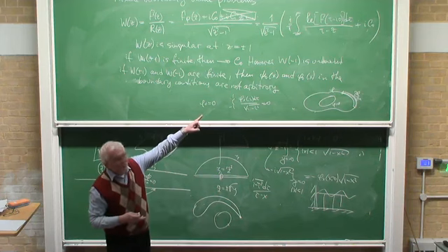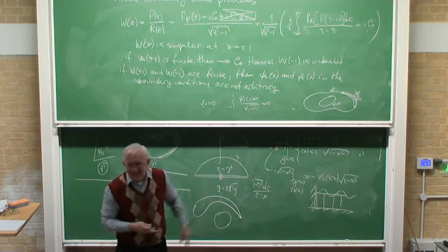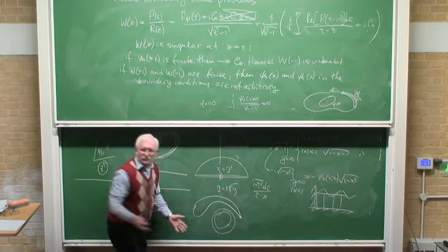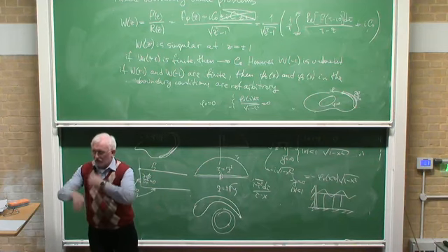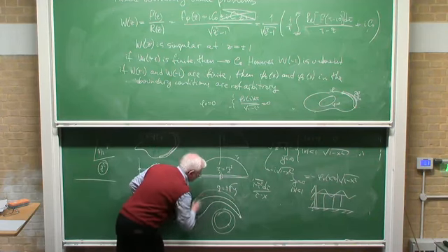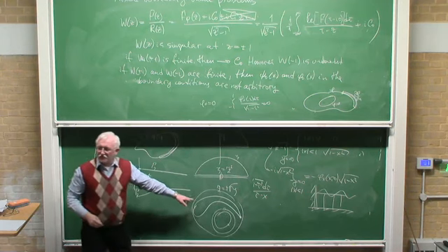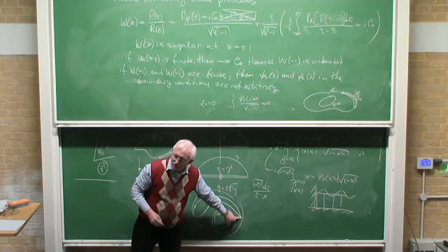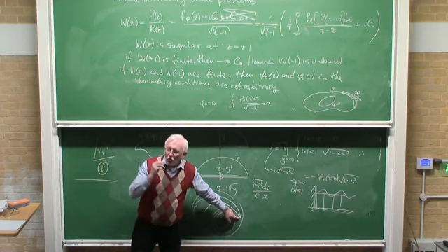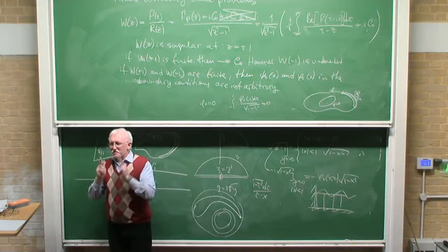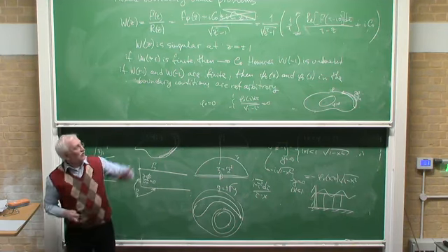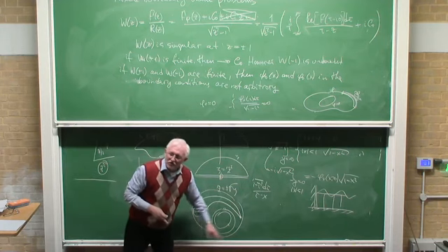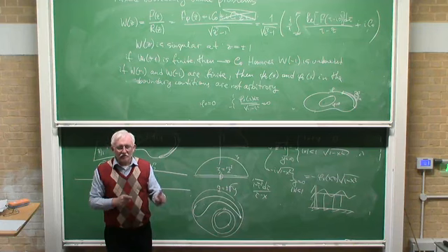For a circle the circulation can be any, around the circle, right? But if you use the same circulation for this profile, it in general gives you infinite velocity at the trailing edge. Only if the circulation has the right value is it finite at that point. But in this problem, there is one singular point.